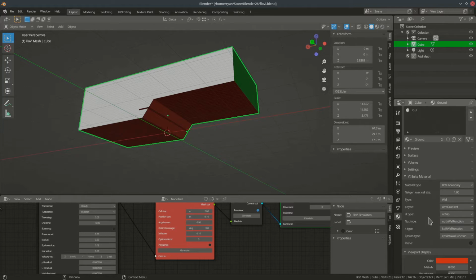They're sort of OpenFOAM boundary conditions. So you will need to know what the boundary conditions are, what they mean, so that you can pick the right one for your particular model. And the OpenFOAM distribution comes with lots of example files, which will give you examples of the boundary conditions that have been used for different kinds of simulation. The vSuite doesn't try and be clever for you in that respect.